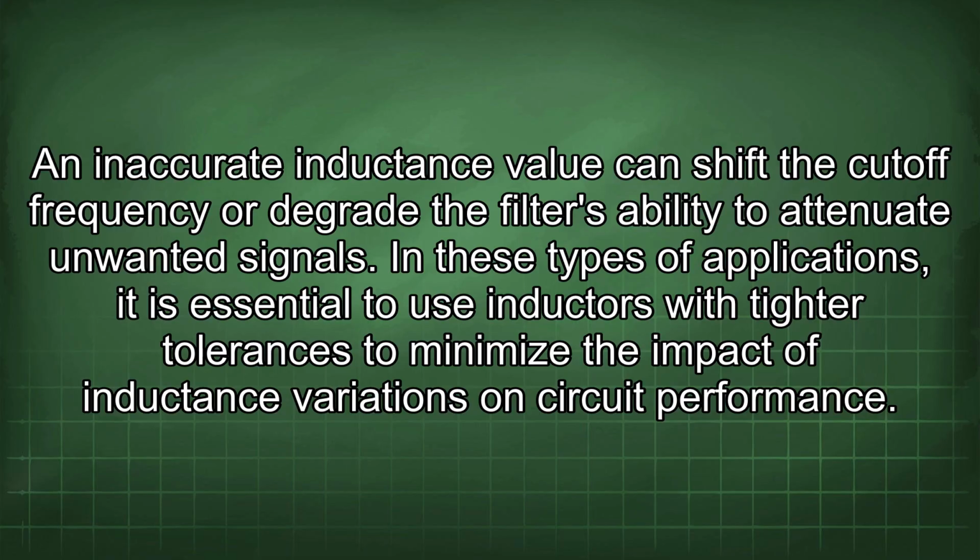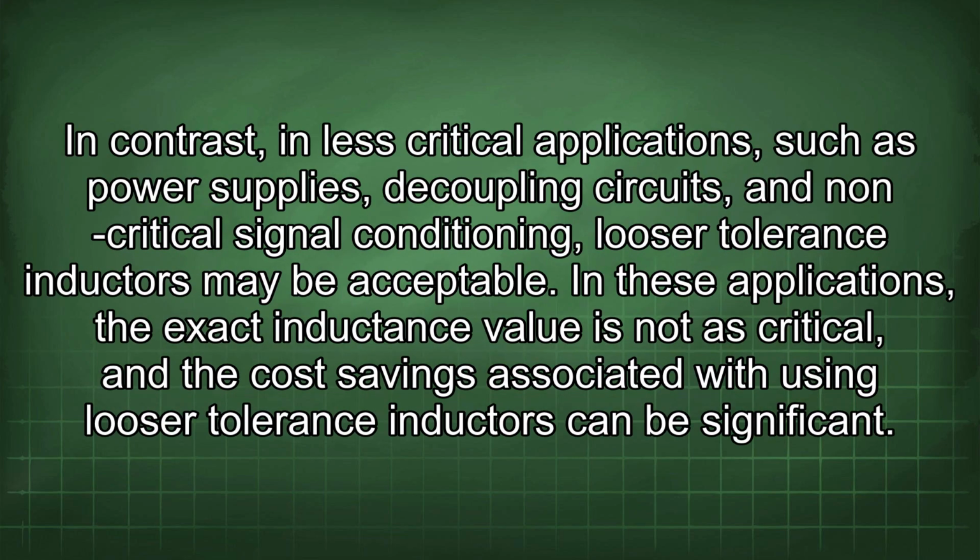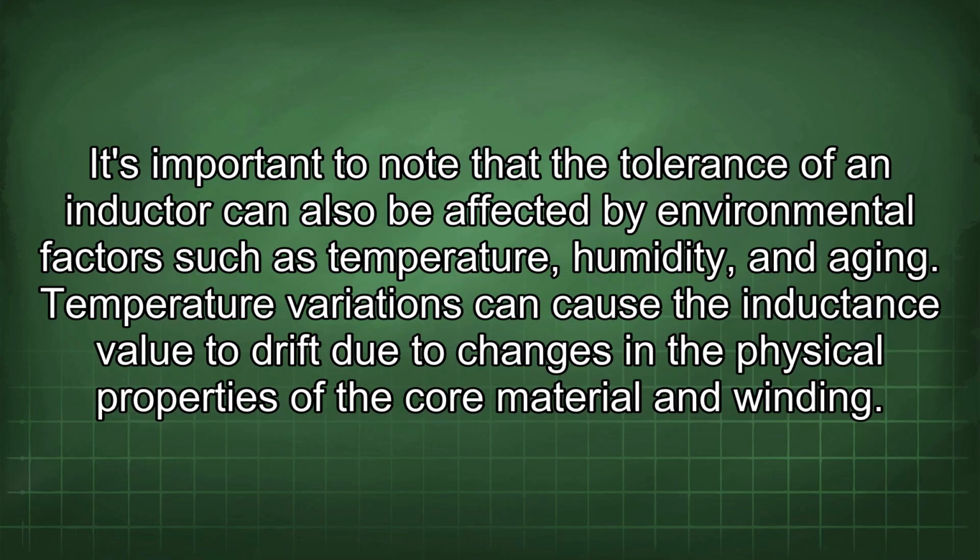variations on circuit performance. In contrast, in less critical applications such as power supplies, decoupling circuits, and non-critical signal conditioning, lower tolerance inductors may be acceptable. In these applications, the exact inductance value is not as critical, and the cost savings associated with using lower tolerance inductors can be significant. It's important to note that the tolerance of an inductor can also be affected by environmental